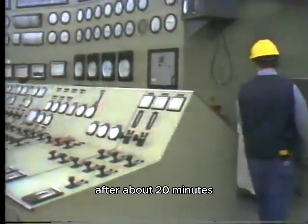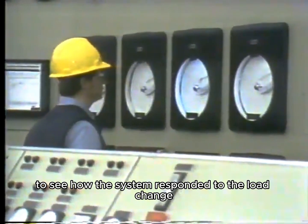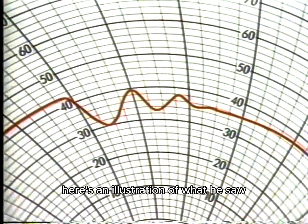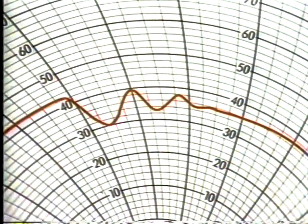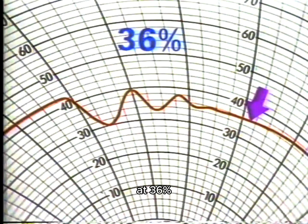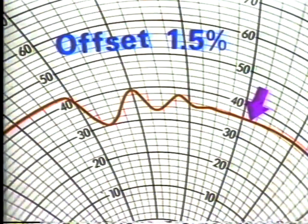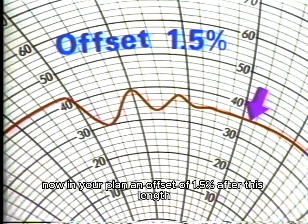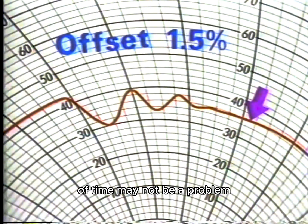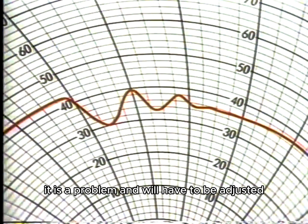After about 20 minutes, the technician went to the recorder to see how the system responded to the load change. Here's an illustration of what he saw. The cooling water temperature has stopped cycling at 36%. There was an offset of about 1.5%. Now, in your plant, an offset of 1.5% after this length of time may not be a problem. But for the purposes of this discussion, it is a problem and will have to be adjusted.